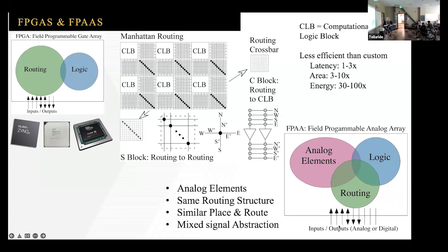What's important about this whole architecture is it was designed for digital circuits. It is actually the key reason why FPGAs became viable. Because you tend to think, oh, it's logic and routing, so it must be a bunch of logic and a crossbar, right? Turns out if you do that, then it scales quadratically. That's kind of a problem. So what they realized is, well, what kind of architecture can I use? And this kind of architecture is really well suited if you're dealing with things that are local and sparse. Because very good local connectivity works well, and I can get some sparse connections as I go out here as well.